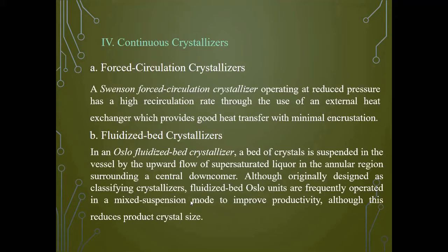Your fluidized bed Oslo units are operating in mixed suspension mode, which is actually the last sample problem that we'll be discussing. Here, your bed of crystals remains suspended by the upward flow of the supersaturated liquor in an annular region surrounding a central downcomer.